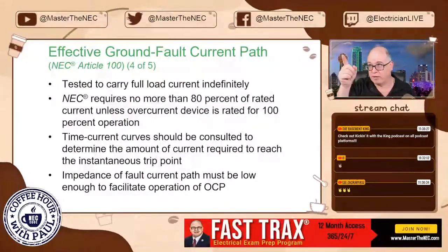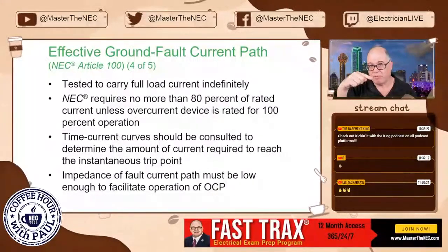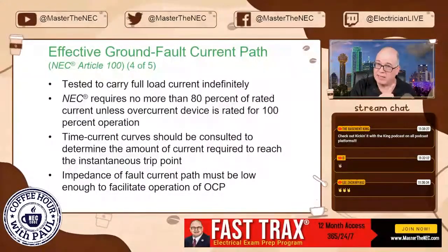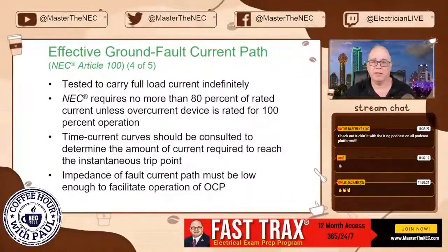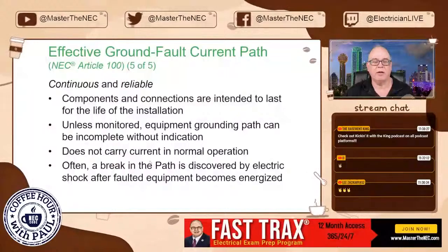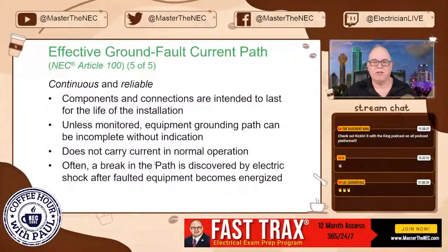If I know the breaker, I multiply it by 80%. If I know the wire, then I can multiply it by 125%. They're reciprocal. There you go. Hopefully that makes sense. All right. Continuous and reliable.